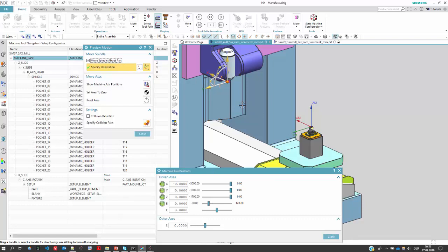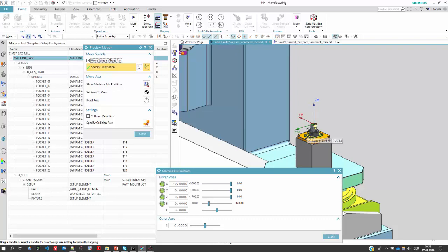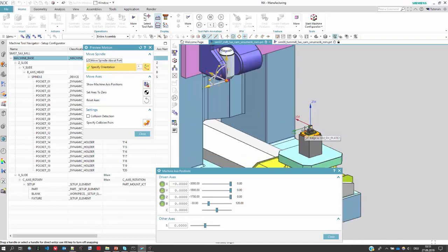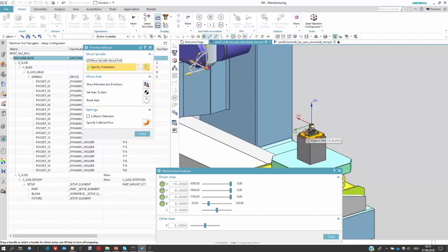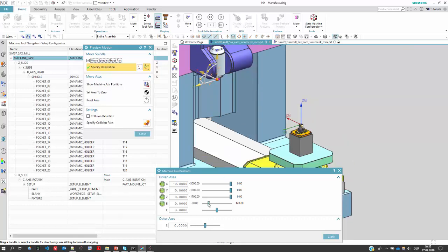When I would like to check now the B-axis rotation, I take my right hand now, look at my thumb where it looks. Now my thumb looks in the same direction as the Y-axis, and the fingers showing my positive direction of this axis now. And in that direction, the rotary axis should rotate. And as you can see, when it rotates positive, it rotates around the Y-axis.